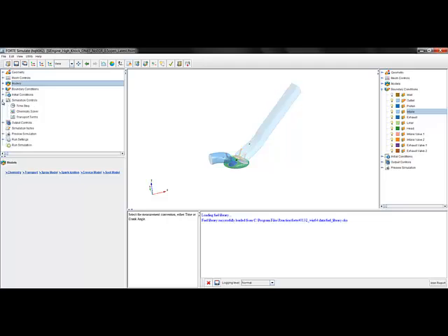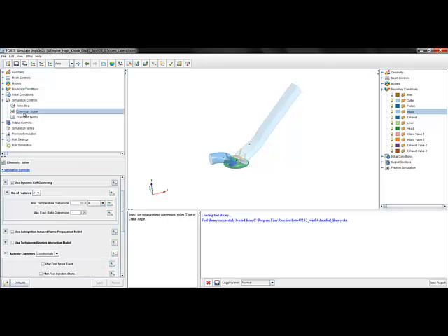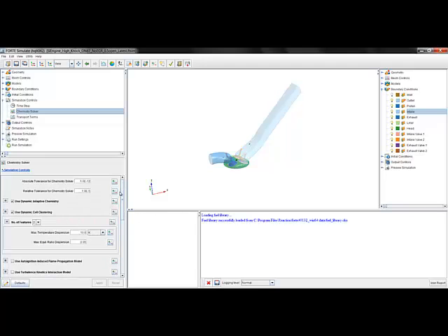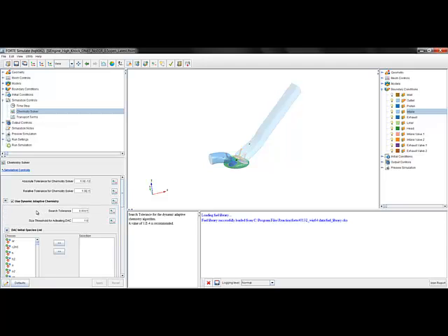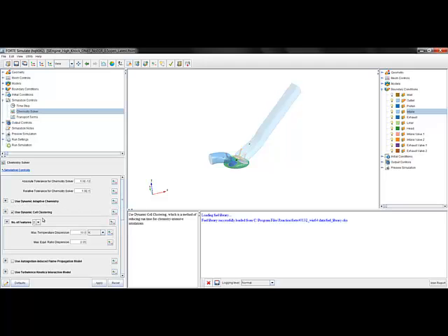Forte has ChemkinPro built inside. In addition to the ChemkinPro chemistry solver, Forte has some unique capabilities to speed up the chemistry solution time even further. Dynamic adaptive chemistry performs a mechanism reduction on the fly, which means Forte uses only the amount of chemistry required for a particular time step. This option is typically only used with very large chemistry mechanisms of 500 or more species, since the base ChemkinPro solver is so fast. So in this case, we would not use the dynamic adaptive chemistry.